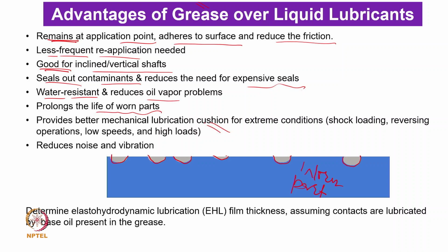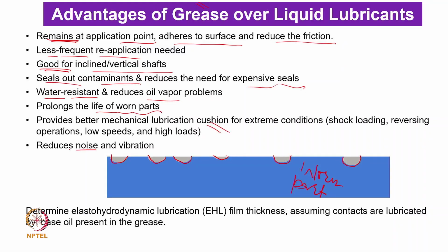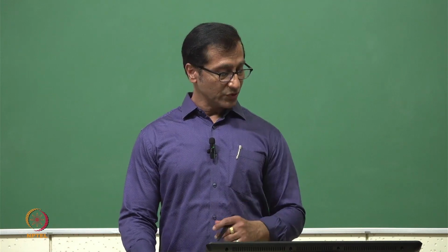In this case, vibration will also be reduced compared to liquid lubricant, and the noise will also be reduced. Even though the part has been worn out and deterioration was happening, the grease is providing extra support to take some stress, reduce the vibration, and reduce the noise level. So this is a very important advantage of the grease in this situation.